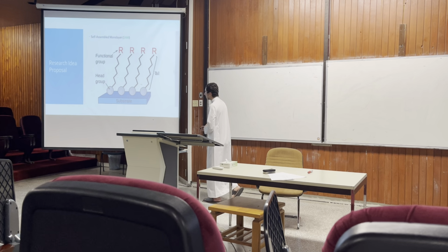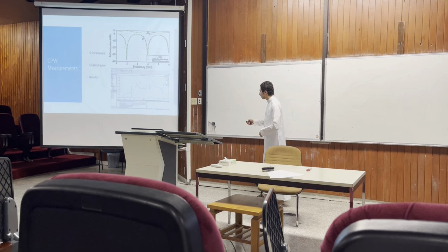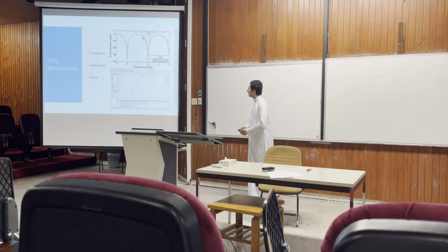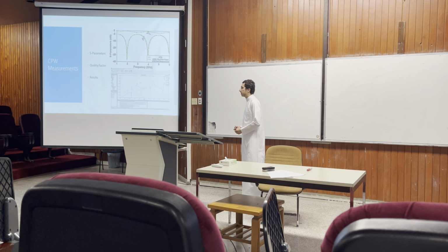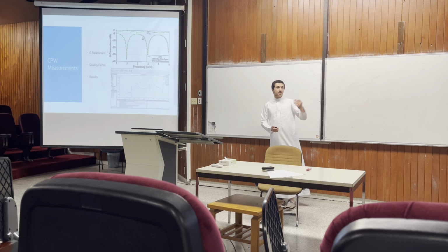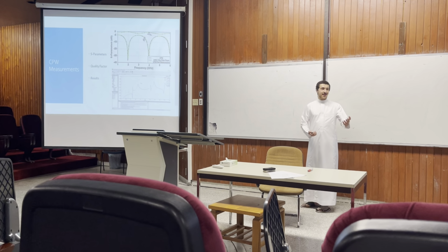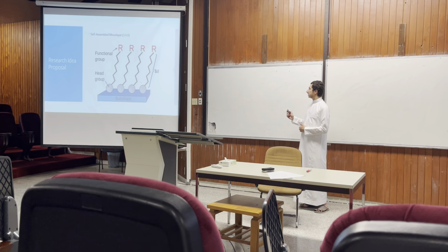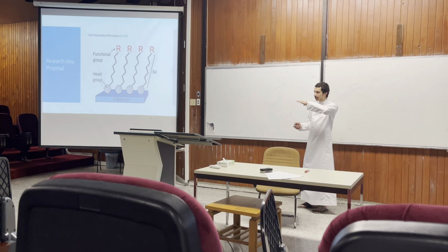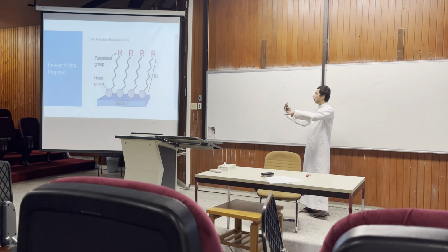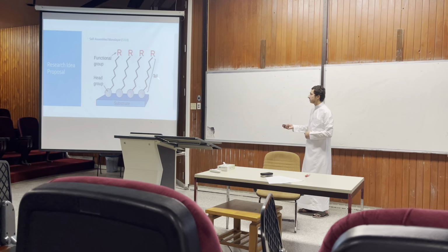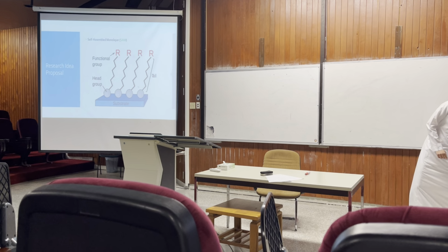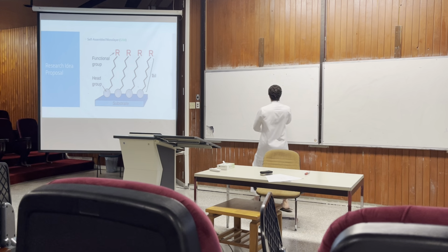Now, okay, to go back slightly, because we have this issue, and sometimes these aren't really ideal in any way, shape, or form. And so, me and Dr. Sadim Rao, actually, well, the doctor came up with the idea, and I'm helping him implement it, inshallah. What we're thinking of is fabricating our typical coplanar waveguide resonator with SAMs on top of them, self-assembled monolayers. What this does is, it helps fix this major issue.